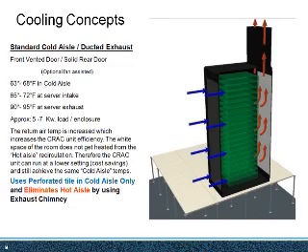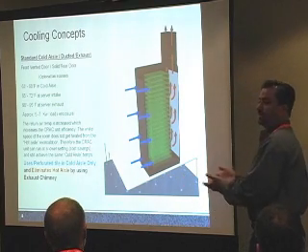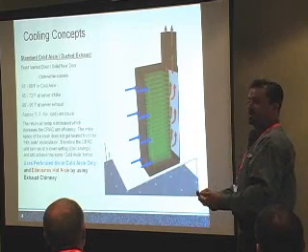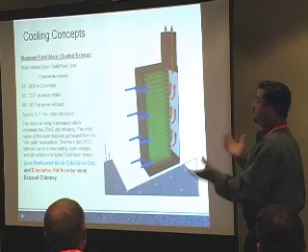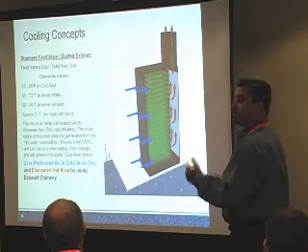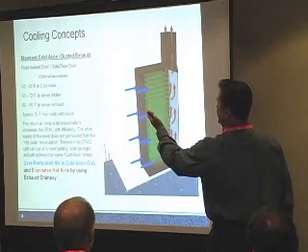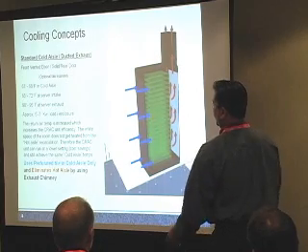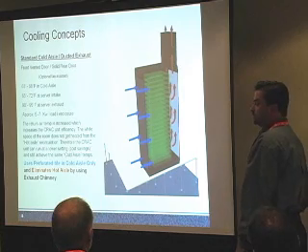So another cooling concept would be to take a standard cold aisle with a ducted exhaust. So now we're eliminating the heat generation inside the room. You're eliminating the recirculation over the cabinet, around the aisles, and just making sure that gets out, whatever method. Again, the back is solid on that? Now this is solid. But as you can see, it's pretty much the same at the cold aisle server intake, and really what you're gaining is efficiency out of the CRAC unit.